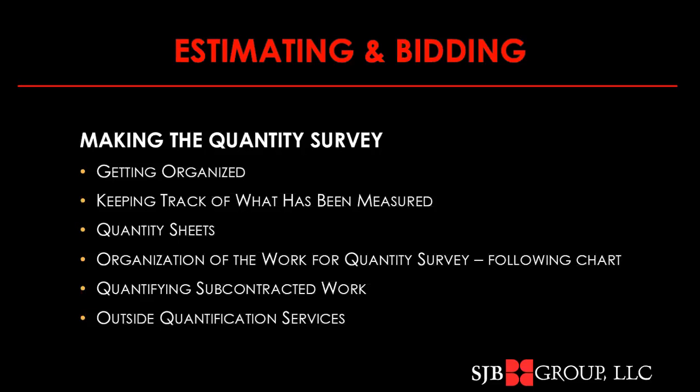Speaking of quantity sheets, if you're looking at a set of plans for a DOTD job, pay attention, always look for sheet 3, 3A, 3B, 3C. You'll find a very orderly quantity takeoff in much greater detail than the bid tabulations in almost every project. It'll be a big help for you as you're doing your own takeoffs to check those numbers.